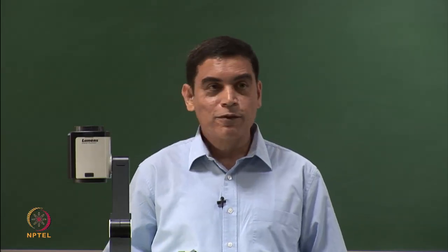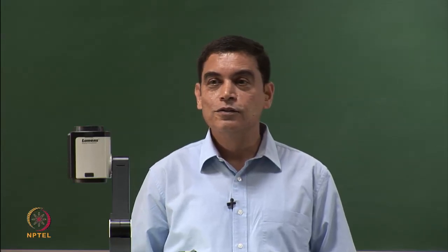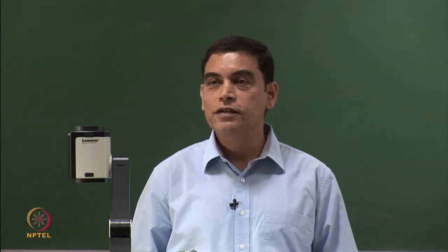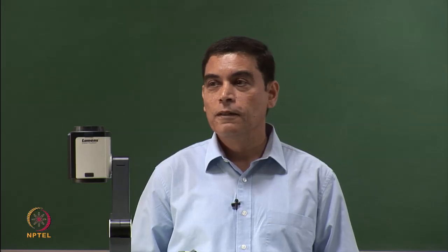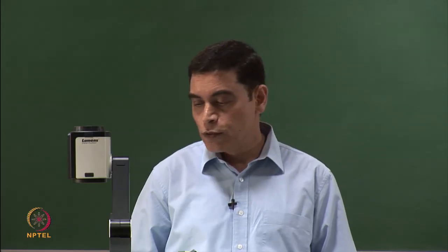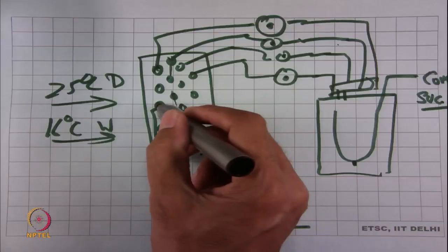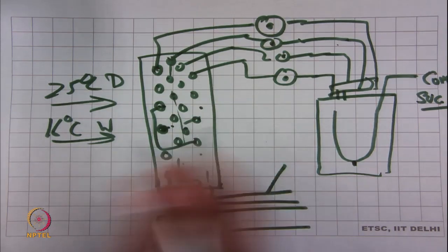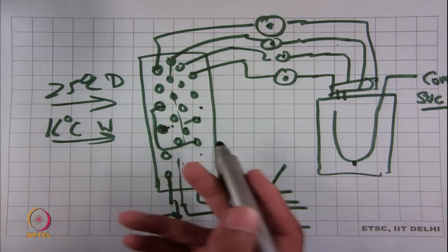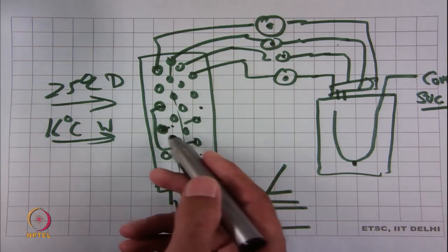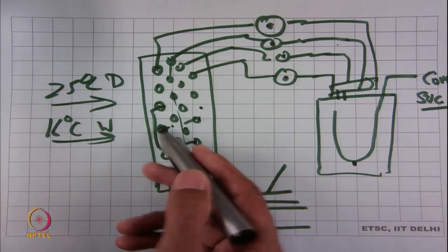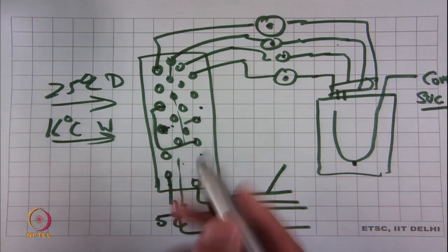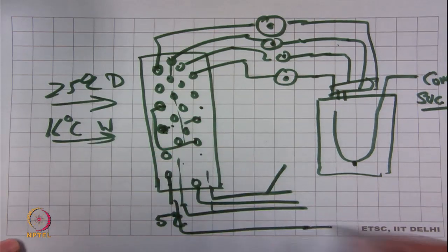So, where were we? We were on designing the evaporator coil. So, the basis of design was scaling up a 3-ton coil. So, that was simple. Then balancing the circuits. So, we know that there is a temperature difference which is very different here than it is over here and somewhere in between. So, we apply a very fundamentally simple rule that we are going to have the same number of tubes on one side and then the other side and expect that to balance out, and then whatever remains we will change the length.